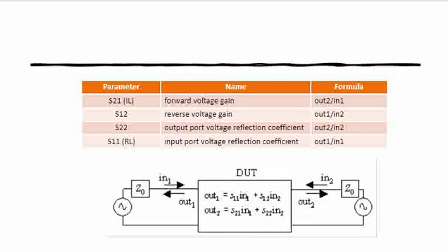In this scenario, there are inputs. There is some signal that is reflected back. So we have talked in the earlier scenarios, right? If there is an impedance mismatch that happens on a PCB, there will be reflections. For example, if you have a wire, there will be a reflection. If you have some chip that is connected in between, there will be a reflection if the impedance doesn't match. So there are reflections on the PCB.